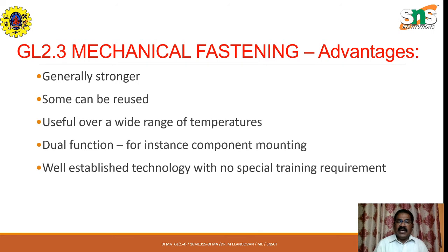Now, between the adhesive fastening and the mechanical fastening, they have their own advantages. Mechanical fasteners are generally stronger, and most of the time they can be reused. They are useful over a wide range of temperatures, whereas adhesive cannot be used at a very low or very high temperature.